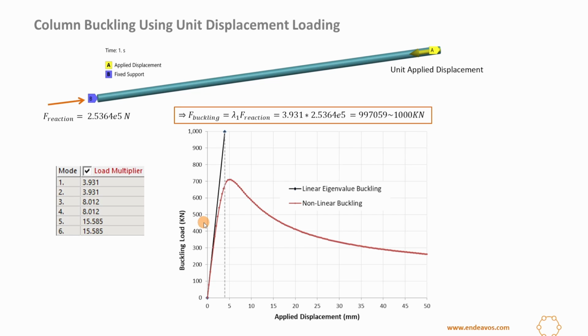Keep in mind that the higher the safety margin is, the more weight we will get. If we are using this in the context of aerospace structures, then the safety margin might be less than 2. So really it depends on a lot of factors. You can use your intuition. There might be design codes that might be guiding the limit load of our structure. So we basically have to use our judgment.